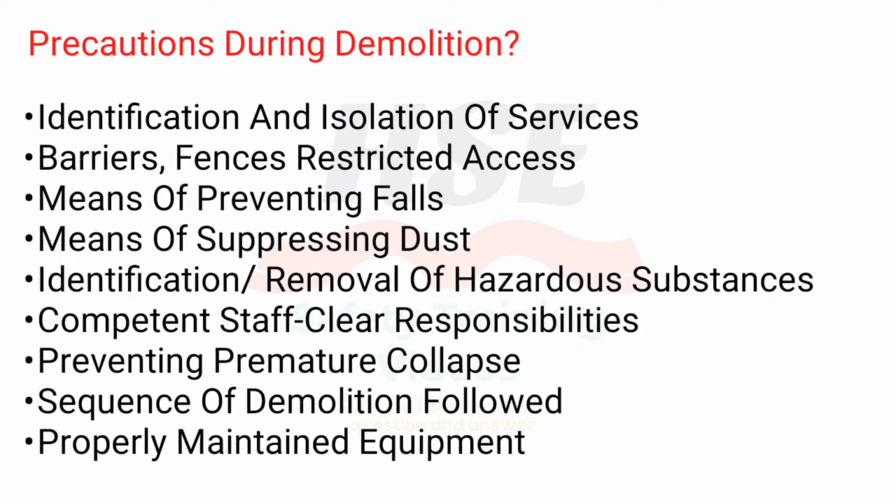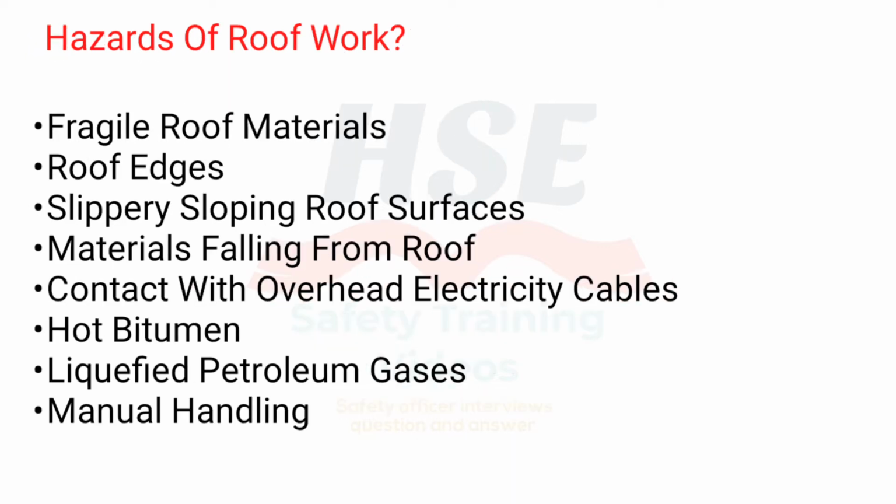Precautions during demolition. Identification and isolation of services. Barriers, fences, restricted access. Means of preventing falls. Means of suppressing dust. Identification and removal of hazardous substances. Competent staff, clear responsibilities. Preventing premature collapse. Sequence of demolition followed. Properly maintained equipment.